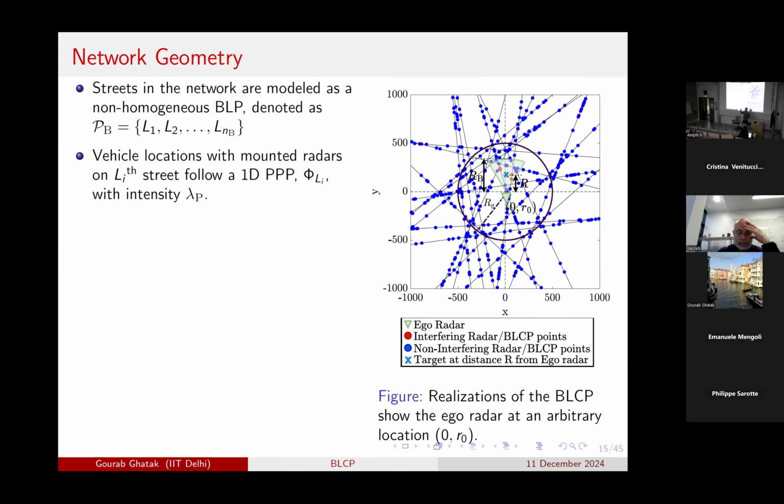But when I am in a dense urban scenario, I would also want to know if there are oncoming targets from other streets which are intersections. They will not be visible except at the edge. Right. So when you reach this intersection, you would want to increase your beam width a bit. Otherwise, you would possibly miss the targets which are coming in.